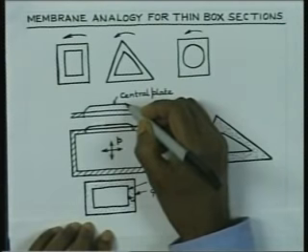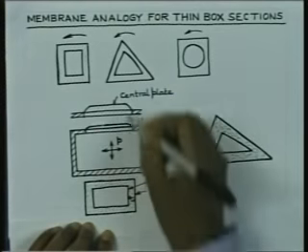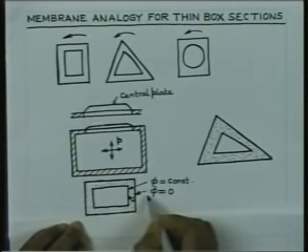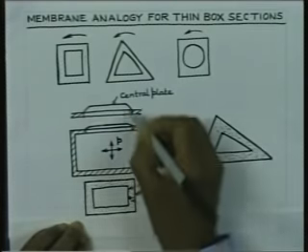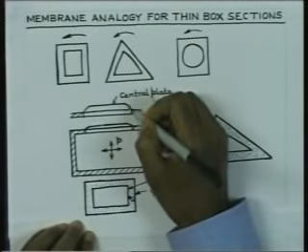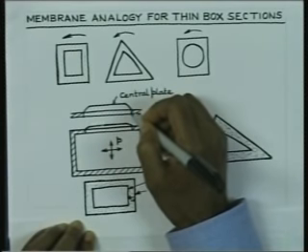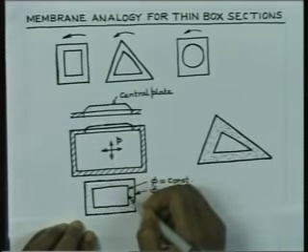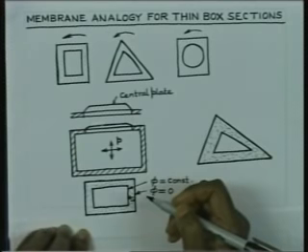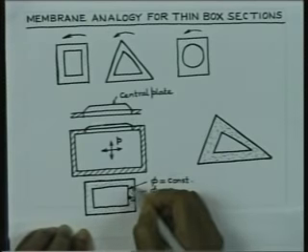So, you can understand now that this is the membrane, if you try to take a section along the vertical plane here, this is the membrane, and therefore, the shear stress is going to be constant. You see that slope, you can approximate this thing by a straight line, and the shear stress is approximately constant, and you find the shear stress to be parallel to the boundary, and it is of constant intensity, or shear flow is constant along this